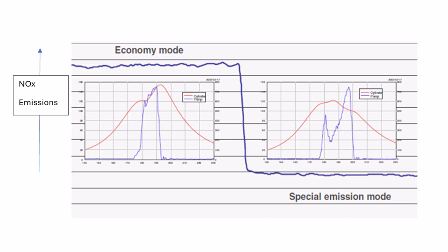So in emission mode, what happens? Again, I see NOx emissions are reduced. I'm talking about NOx emission, not the sulfur emission. Sulfur emission is different. For sulfur emission, the simple thing is either use low sulfur fuel or use a scrubber. NOx emission, economic mode: higher SFOC, normal injection, normal pressure, compression, and peak pressure. Higher the peak pressure, lower the specific fuel consumption.